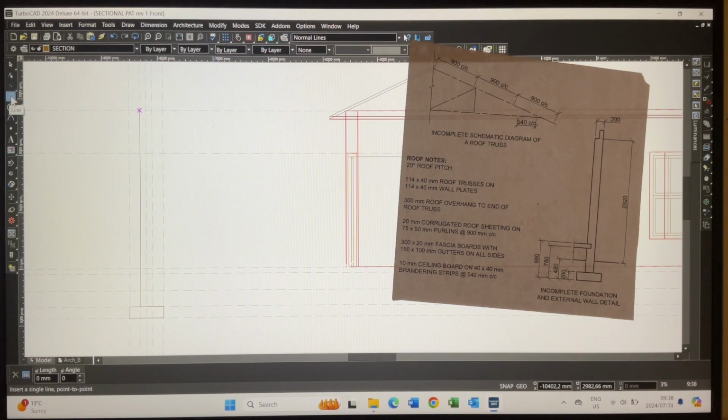Right, I'm going to draw a little line coming across from there to the middle of the wall. I'm going to press my parallel lines again, and I'm going to go 86, tab 86, that's the size of one brick coming down, so I'm going to click there. I can now draw in a line coming down over there from there to there, clicking across from there to there, and I'm going to click a line coming all the way down to the bottom. Okay, we're not going to need that line coming all the way down. In fact, let's not do that. Control Z.